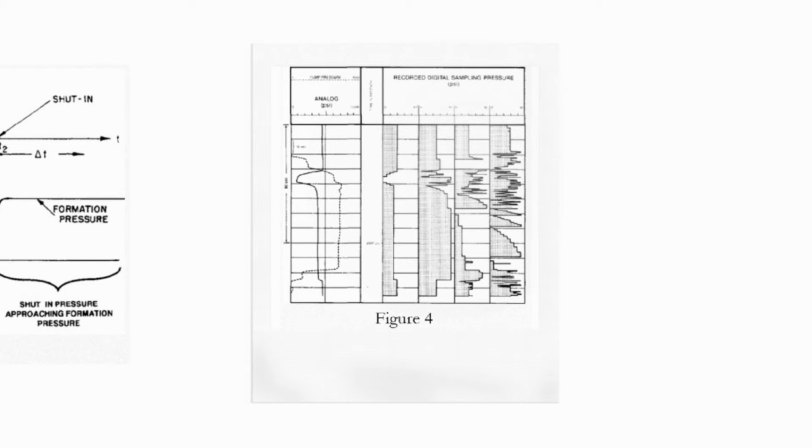On the right are 4 narrow tracks displaying the thousands, hundreds, tens and units digits of the measured pressure. For example, after 80 seconds, the formation pressure is 3927 psi. It is obvious on the units track that the pressure is increasing and actual formation pressure has not yet been reached.